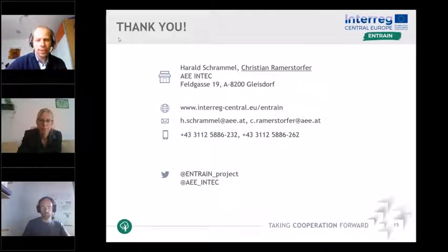So this is already for plants of more than maybe 5 megawatts or in this range. Usually the legal emission limits consider that, so that you have higher allowance for smaller plants, so that it is not necessarily needed to install an ESP for plants of that size, Matteo.